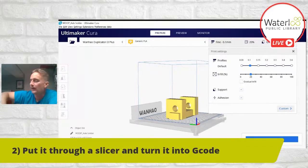It'll be warm. And if it didn't have a heated bed, if it didn't have a heated platform that it printed onto, those first few layers would eventually start to cool. They would deform, they would shrink, and your 3D print can actually pop off your platform. So that's usually fixed by having a warmer platform. You have different temperatures depending upon the plastic, and so your 3D printer will heat up its platform to a specified temperature to help keep the plastic stuck on there. But even then, depending upon your platform and the material that it uses, that doesn't always work. So adding something like a skirt can help.